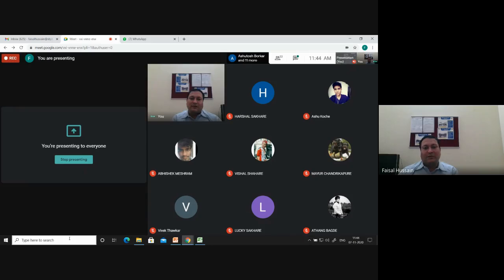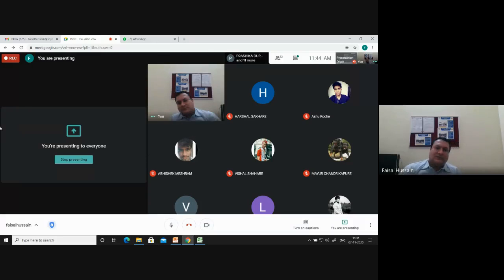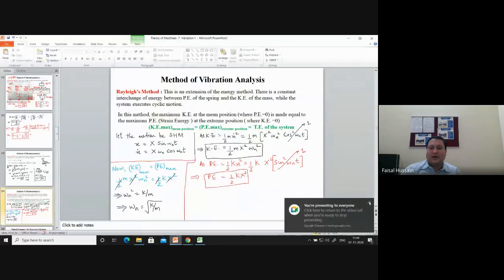Either we use equilibrium, or energy, or Rayleigh's method, for a free spring mass system the natural frequency is ωn equal to the square root of k by m. So after this, let us move to the next part,